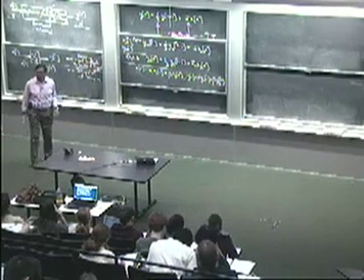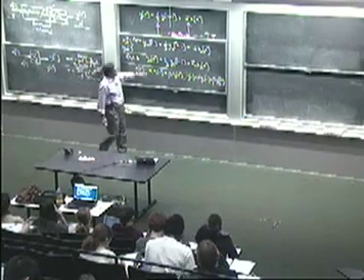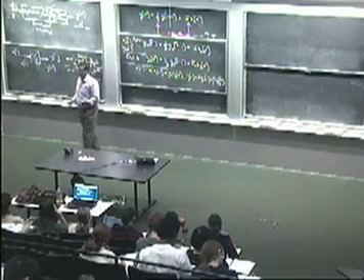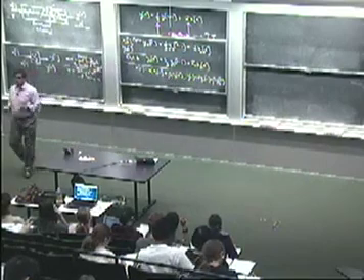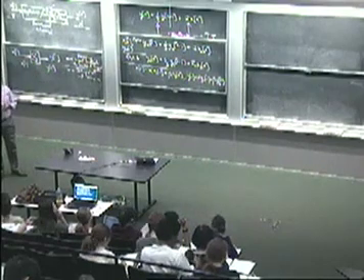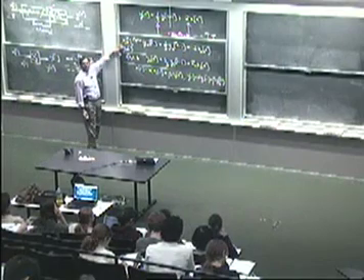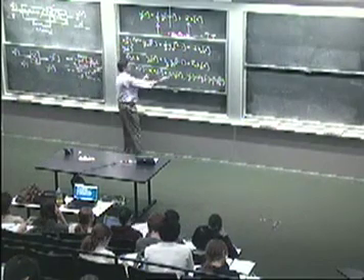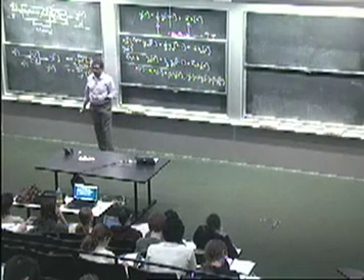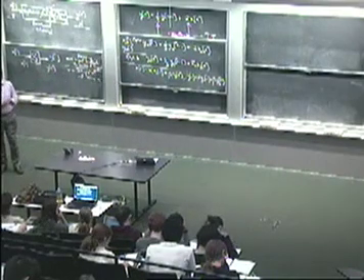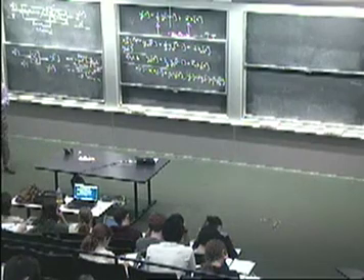So when you substitute these in, you'll find that x[n] defined this way and y[n] defined this way will actually satisfy that equation. Okay? So this is what superposition requires you to test. If it's true for every possible pair of experiments here and every pair of weights alpha and beta, that the superposition satisfies the equations governing the system, then what you have is a linear system. Okay?